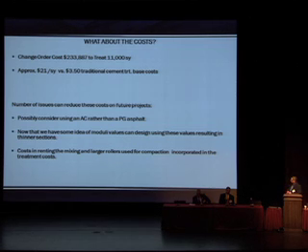Because, again, the contractor didn't have some of these bigger pieces of equipment, a lot of those costs are incorporated into the square yard costs. So we didn't have any 20-ton rollers on the job because he wasn't compacting 11 inches, he was compacting 6. But again, you eliminate quite a number of processes, so there's a cost savings there that would probably bring that price down, probably in the neighborhood, I'm just running some numbers off the top of my head, of $12 to $15 a square yard.